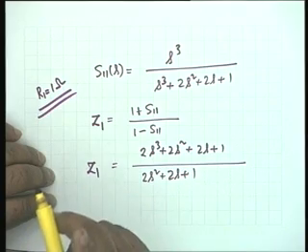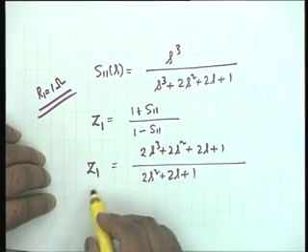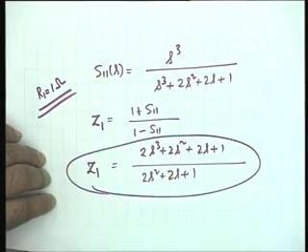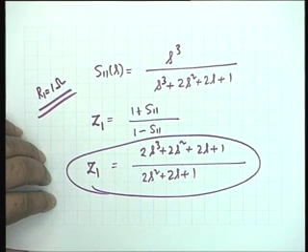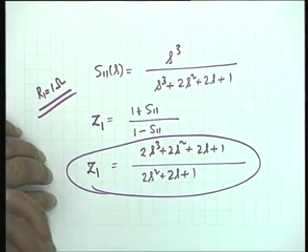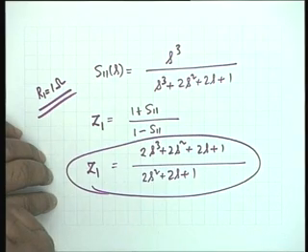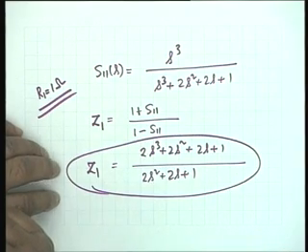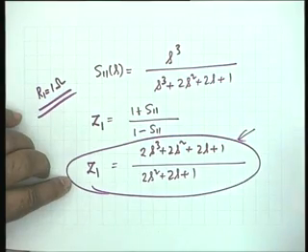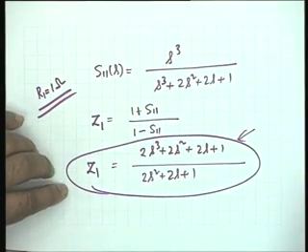And the last task in the process is to synthesize this impedance Z1. And it is a beauty of Darlington synthesis that the constraint that Z1 shall be a lossless network terminated in a resistance which is equal to the resistance at port 1, that is 1 ohm, has already been taken care of. And how to do this I shall demonstrate next time. Okay?